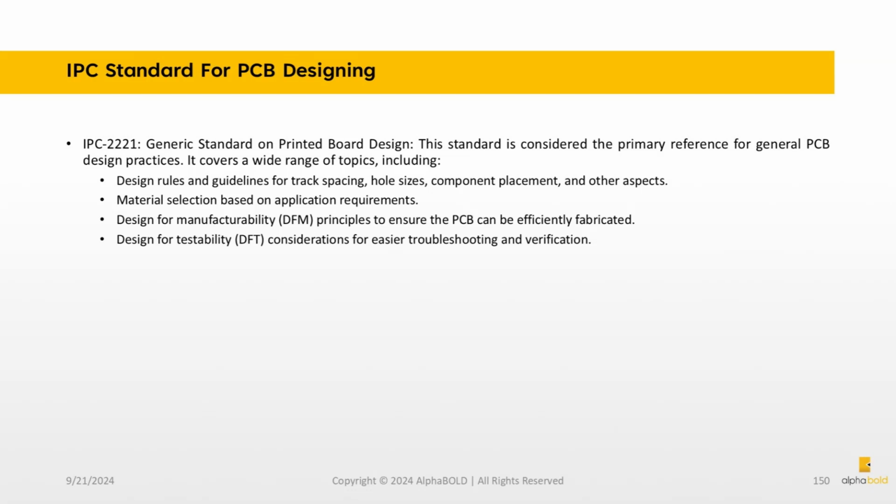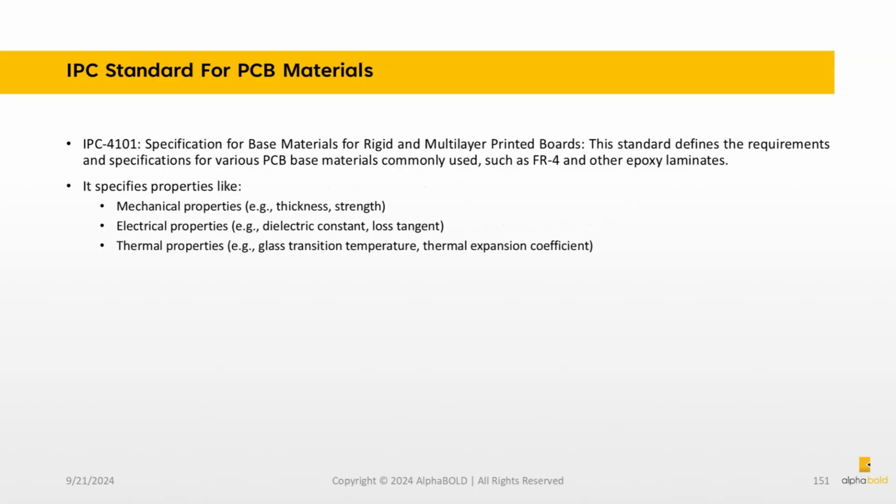Design for manufacturability, DFM, principles to ensure the PCB can be efficiently fabricated. Design for testability, DFT, considerations for easier troubleshooting and verification. IPC 4101, specification for base materials for rigid and multi-layer printed boards.